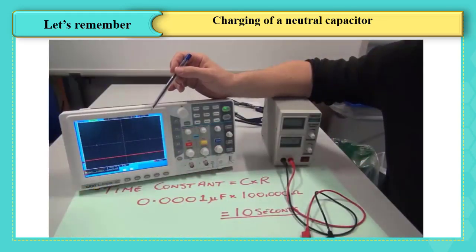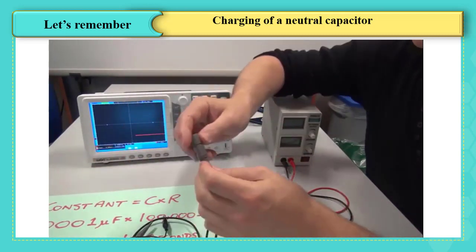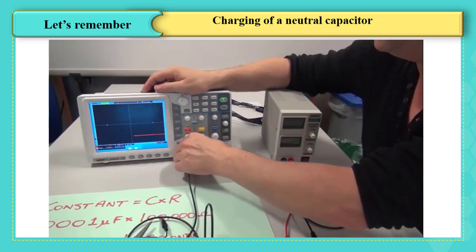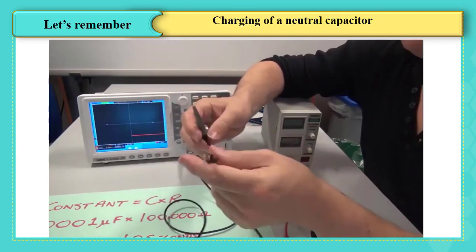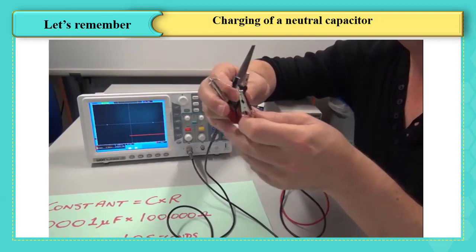And here we have the oscilloscope, and we're going to use the oscilloscope to measure the voltage across the capacitor. We need to connect the scope. We have two ports here, channel 1, channel 2. It's simply push and twist. The probe itself has a ground clip, and that will connect to the ground of your circuit.